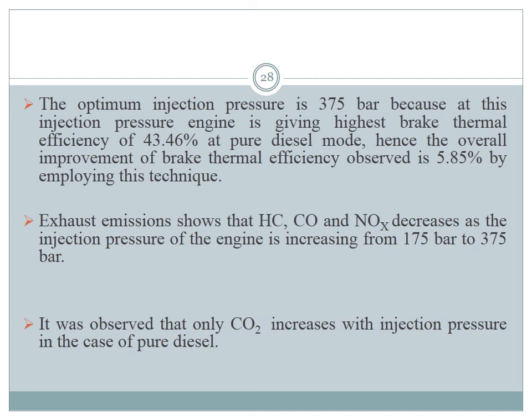We have also concluded that exhaust emissions show that hydrocarbon, carbon monoxide and oxides of nitrogen decrease as the injection pressure of the engine increases from 175 bar to 375 bar. It was also observed that only CO2 increases with injection pressure in the case of pure diesel.